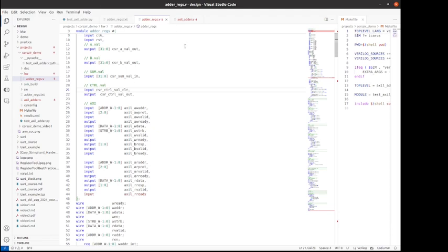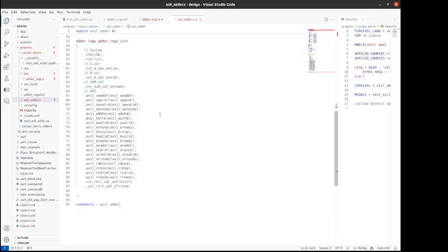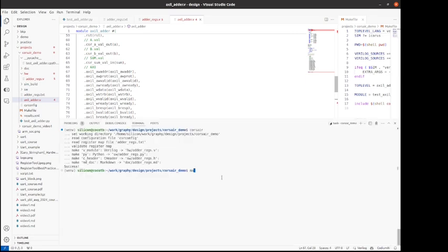So let us go back to our accelerator. This is how I defined the handshake between those two ports. I defined start, which is a control bit from the CSR, and I defined the acknowledgement for it. So when the start is accepted, we will do the operation. Then we acknowledge the start as well. Those two ports I connected here. Let me run the design.